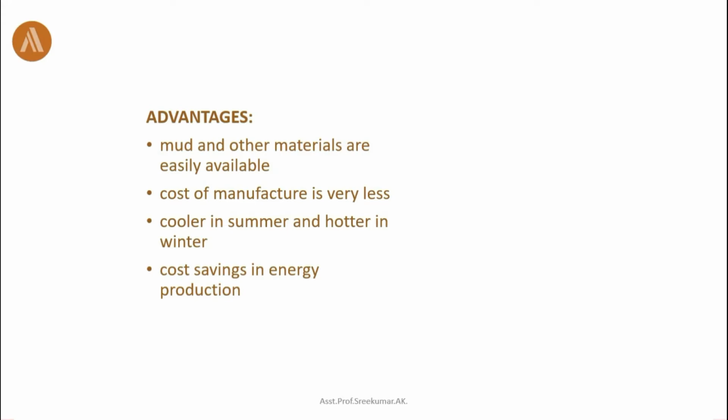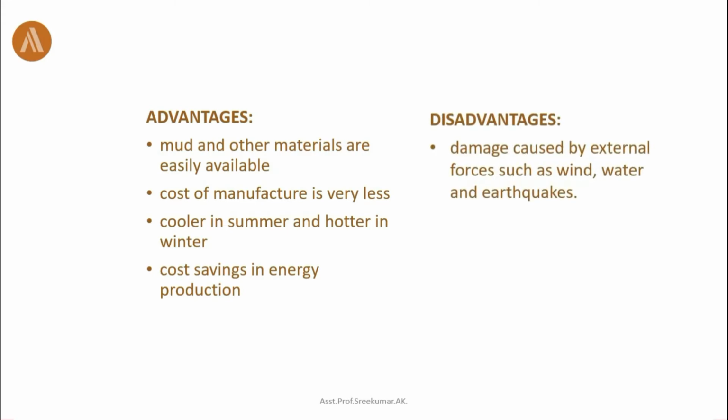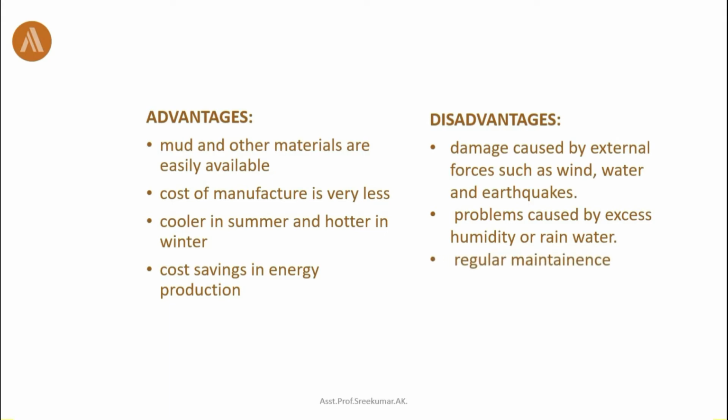And there are a few disadvantages as well. First, damage can be caused by external forces such as wind, water, and earthquakes. Second, problems caused by excess humidity or rainwater. Third, it needs regular maintenance. Fourth, there are chances of cracking of walls in summer. So these are the disadvantages of using adobe for construction.